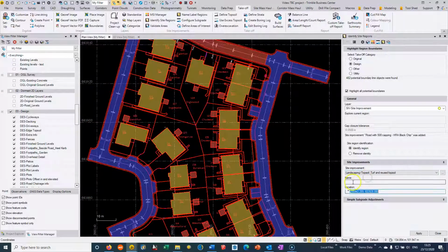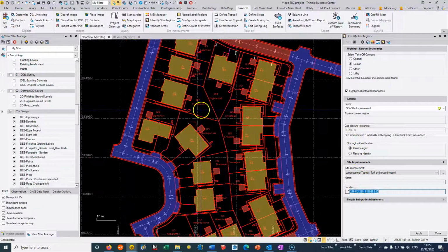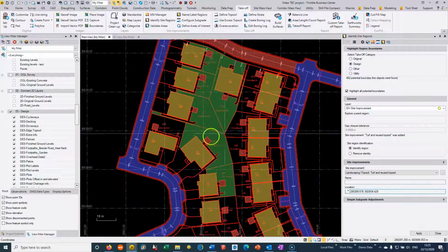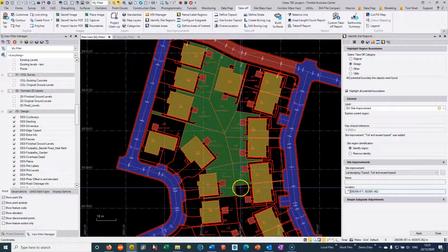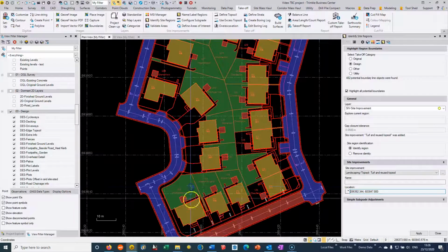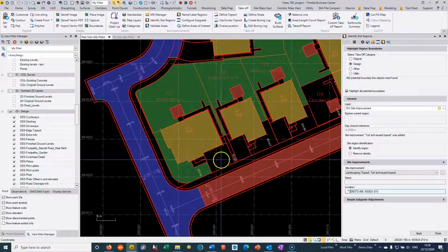So we might want to use the topsoil. So what I would probably do here is I would normally take the fences out of the boundary, so it just floods out in its entirety. But if not, then we just need to drop a seed point into each area. And basically that's just marking where we're going to reuse the topsoil after the topsoil strip.